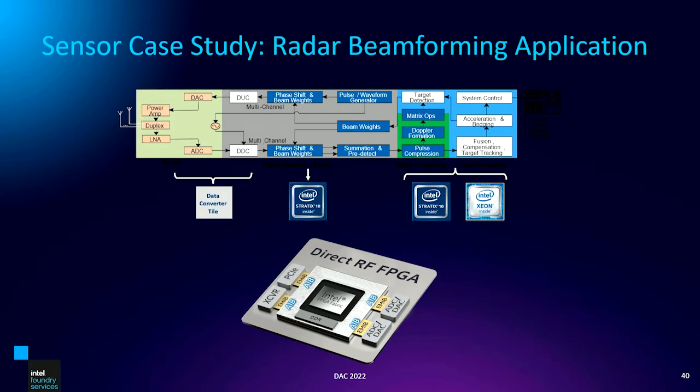If you look at the block diagram closely, which is probably not possible, but if you squint really hard, what you can see is that the RF is separated, and they're creating software-defined radios. In this case, they've done software-defined radios with FPGAs, and this enables them flexibility in adapting their DSP algorithms as well as different RF front ends. So it's a chiplet example of an FPGA plus an RF front end.